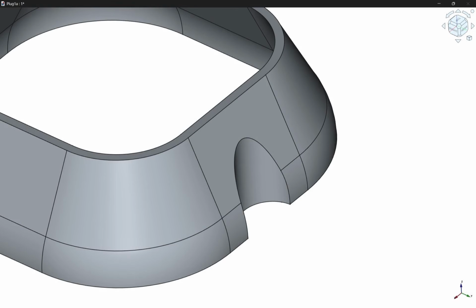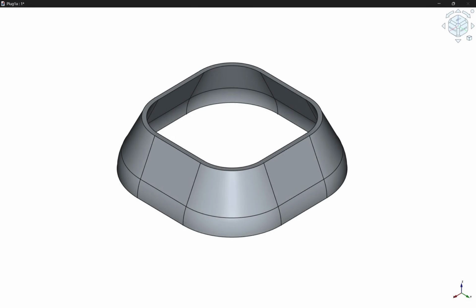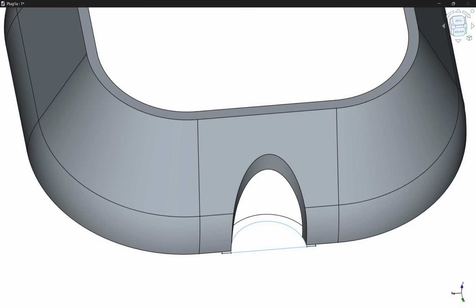An alternative workflow is to approach the subject from the side, creating the initial shape with the additive pipe operation. This eliminates the need for applying the thickness altogether. The sketch that we used for the loft in the previous workflow, we can use that as a path. We just need a cross-section sketch to define the profile to sweep around it. This allows us to create the shape with a single additive pipe. Then we can tackle the finger well. Again, this is removed with a pocket.